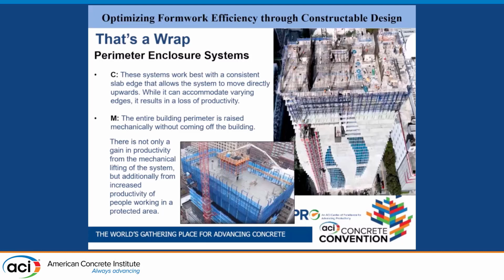From a mechanization standpoint, all these things get picked up by the crane. It creates a cocoon around the building, which is nice from a safety standpoint, from a material falling standpoint. But one of the big productivity gains from it is that people feel safe. They feel that they're working down on the ground. Like they could be 50 floors up in the air, but they have the effect of working down on the ground. And that has a big change to your mindset. So you're just not in the active mindset of falling the entire time.